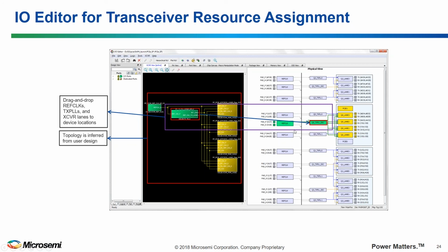We have an I/O editor, and in Libero SoC PolarFire we've made some changes to the I/O editor, particularly in the area of the transceivers, to make it easier for you to implement your designs and place the transceivers, the reference clocks, the PLLs and so on. So you'll see a schematic view that shows a representation of your transceivers, your reference clocks, and your PLLs that are being used in the design.